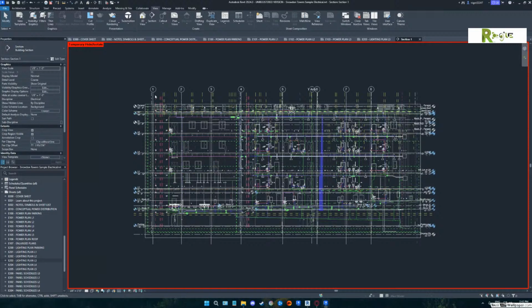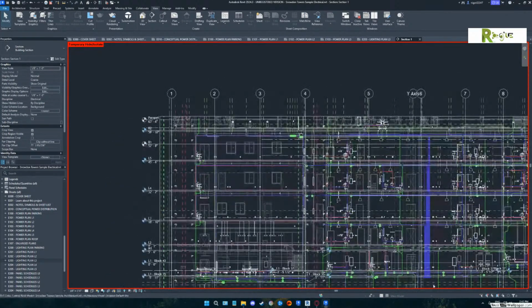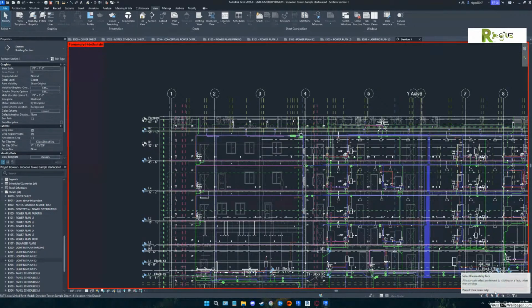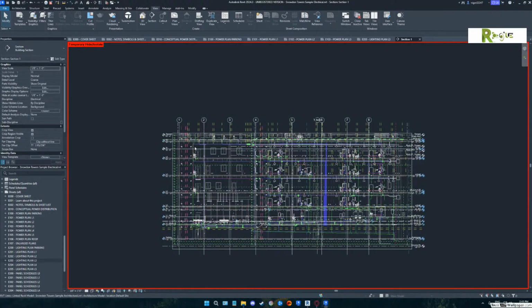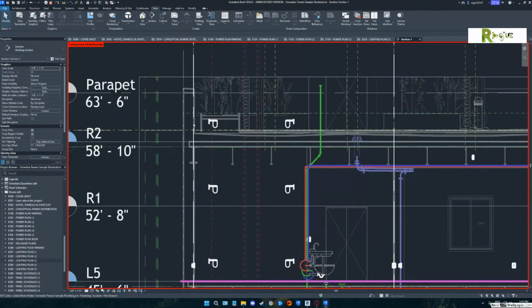But what he does have the problem is there are 8 or 7 grid lines on top of each other. If you pick that grid line, it's going to select the whole. Nope, not number 2, the number 1. Pick it. Can't pick it. It's because your locked links are on. Oh yeah. No, it wasn't. Still can't pick it. If you still can't pick it, it's because your locked pin dot is on or something. Underlay elements. Oh, no. You need to select it inside the crop boundary. You can't select it outside the crop boundary. Inside. Zoom in closer. To that right area. Here. Yeah, that's where you need to pick it at.